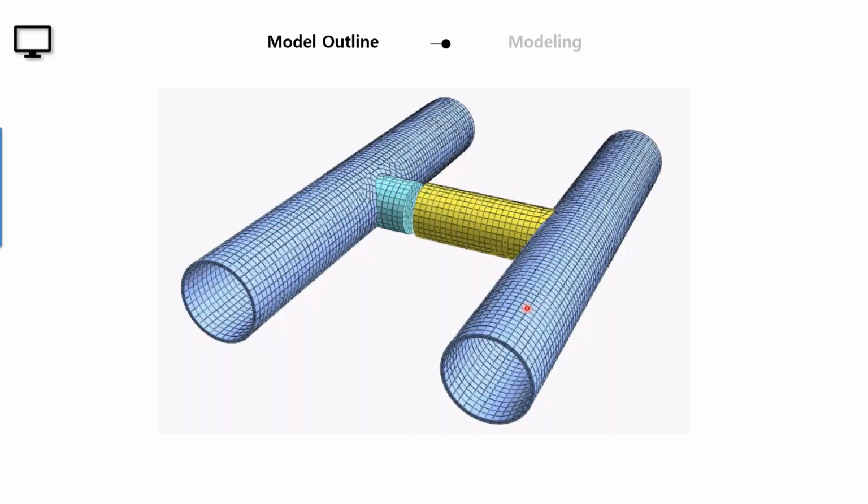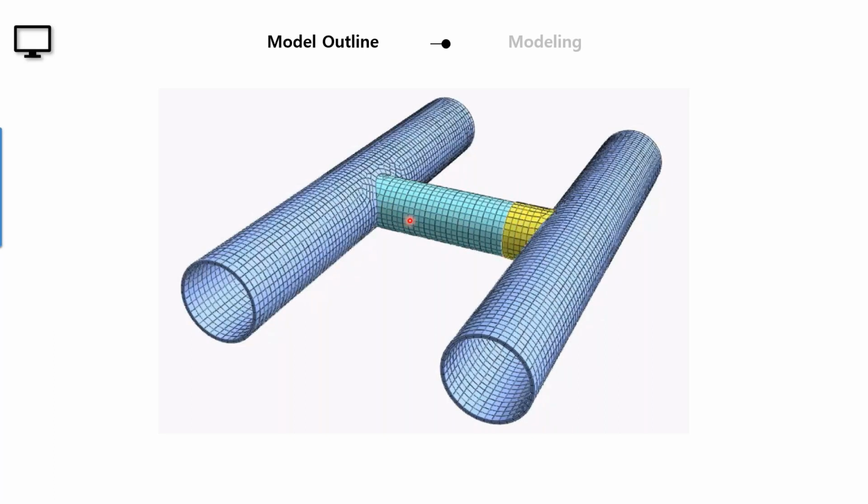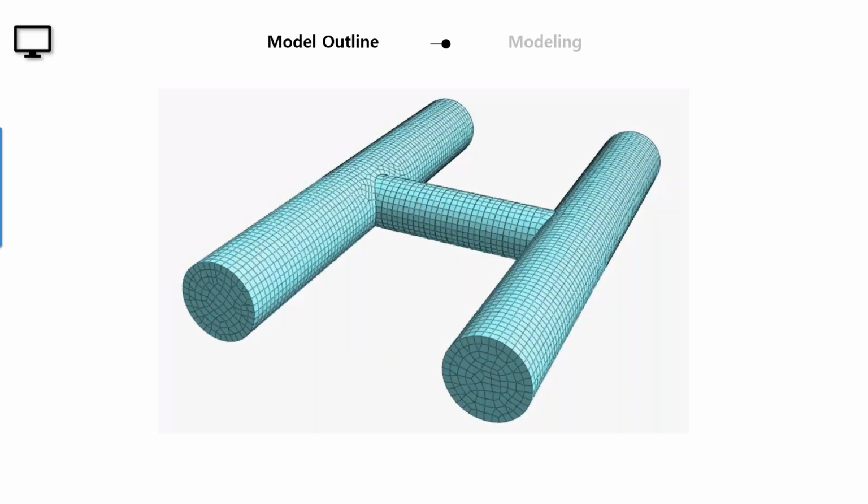At first, the right tunnel is excavated, followed by the left tunnel, and then the excavation of the cross passage will start from the right and proceed towards the left. You can see one stage gap, which means 80% relaxation is applied in that stage, followed by the application of the tunnel lining in the next stage. That's the idea. So let's create the model.